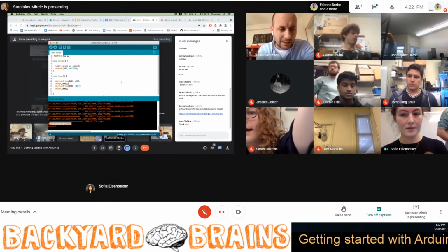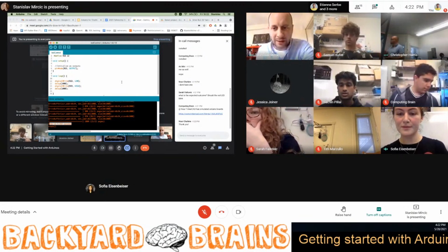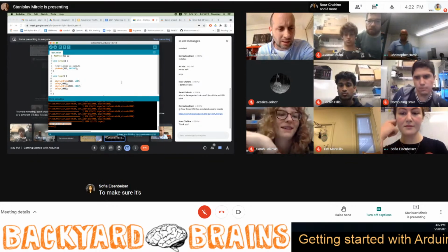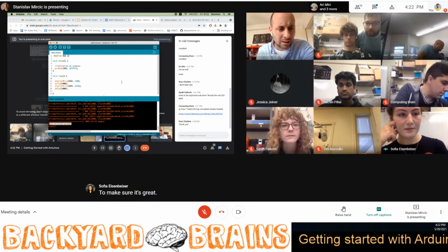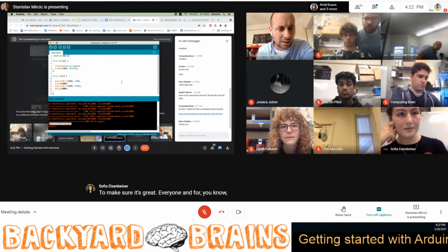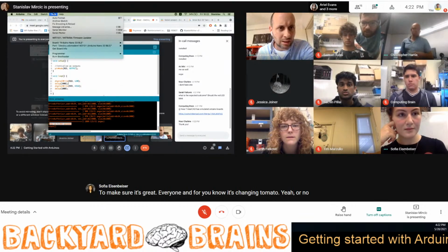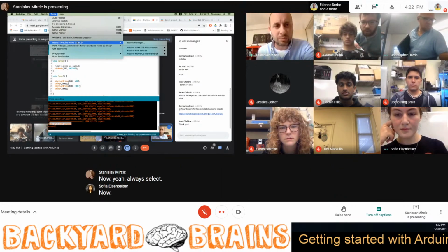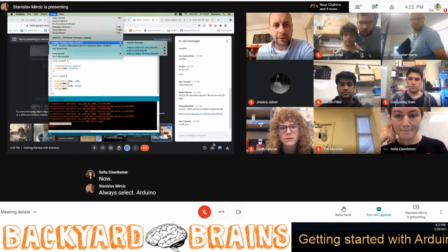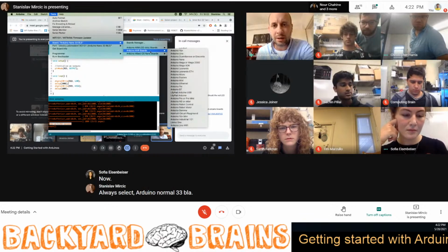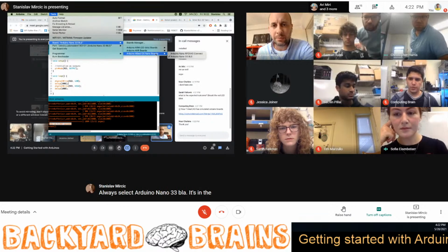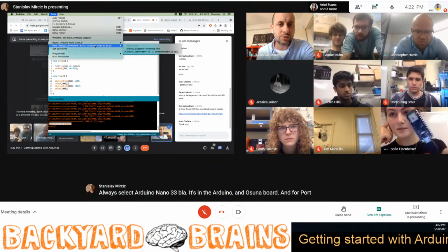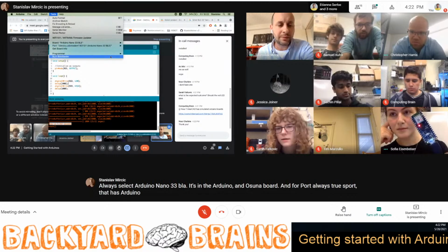Who? Me and Ari. Okay, I didn't have Arduino Nano. So make sure it's the right Arduino board. You don't know, you're doing a Nano. You have to change it to Nano. Arduino boards right there. Always select, for board, always select Arduino Nano 33 BLE. It's in the Arduino Mbed OS Nano board. And for port, always choose the port that has Arduino Nano BLE.